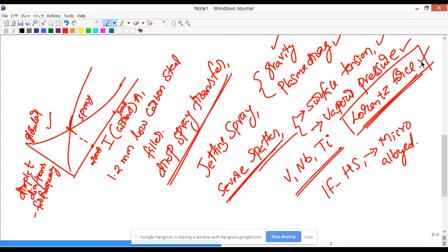So question 7, the enhanced uniform elongation in TRIP steel is due to the stress-induced transformation of austenite to martensite. I already addressed this question in the forum. Someone asked about how this stress-induced transformation of austenite to martensite increases the ductility. So I already explained various mechanisms.